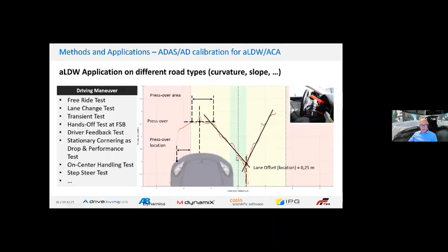Just to give you an impression, this is an objectivation of our system. Even if you have here a center guidance, for example, and you come out of the middle line, you have a certain torque input to the driver to keep the car in the center lane. You have a so-called control-free corridor, and here this is a test of overpressing: the design of the overpressing, the gradients, the plateau, and how you switch off the torque. This must be designed, and this needs a long time on the road. Now, with each car and with each steering, you should adapt that, and this is very time consuming. This can be done on a driving simulator.